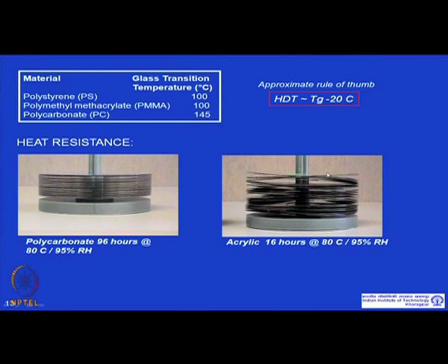when you make a part, it has its own load, it has some weight. So, it has its own load, and when you stack these discs, the lower one will also have load from the top. So, at 80 degree itself it is deforming, which means it should not be used. A disc made of PMMA will not survive a temperature of 80 degree centigrade. So, this is what it signifies.